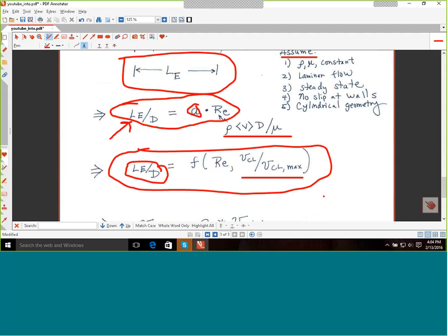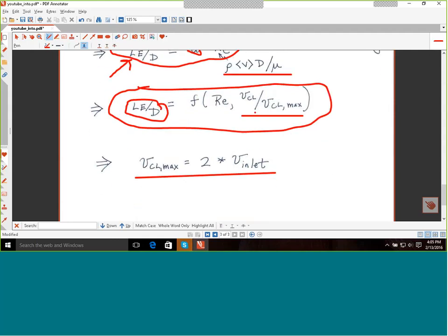We're going to do it computationally, but essentially using numerical experiments, we can pick various liquids using the physical property database in COMSOL, and we can then use various flow rates and plot our data, and we can repeat that for other types of fluids that are in the physical property database in COMSOL, and as I say, basically do numerical experiments and try to see if we can determine this correlation.